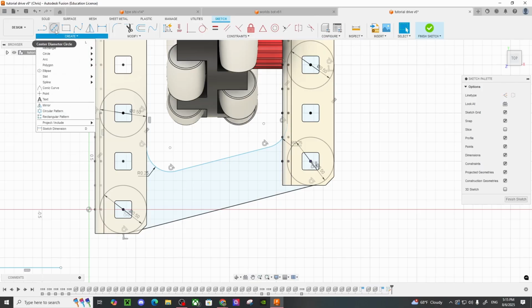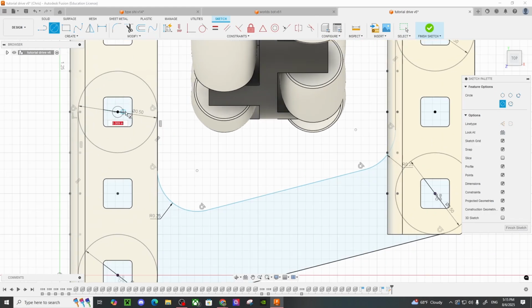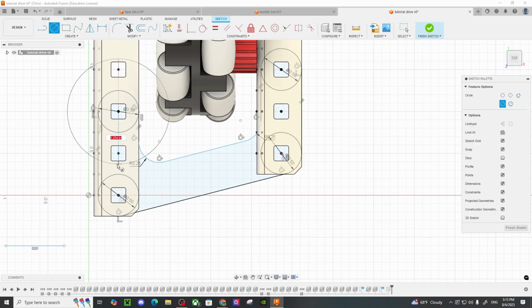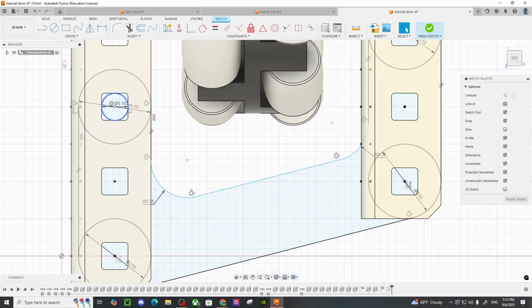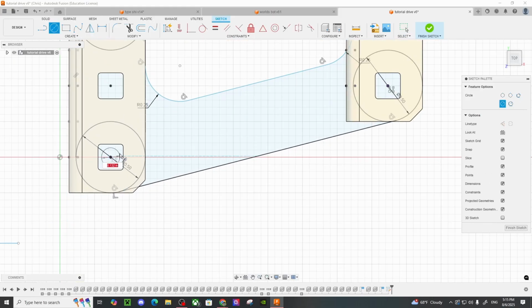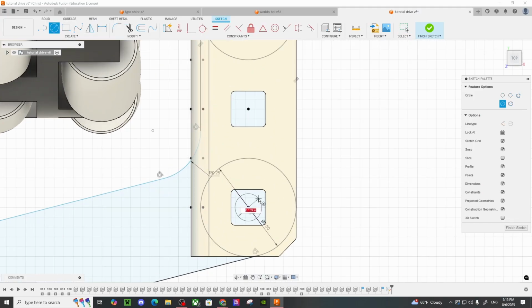Now we're going to get our screw holes in. As I said before, I want screw holes here, here, here, and here. Since this is the drivetrain gusset, I'm also going to have another screw hole in the midpoint here. For the outer ones where we already have the geometries projected, just do what you did in step 1 before: hover over the point with the circle tool, and for screws, 0.183 works pretty good. It's not too loose or too tight.